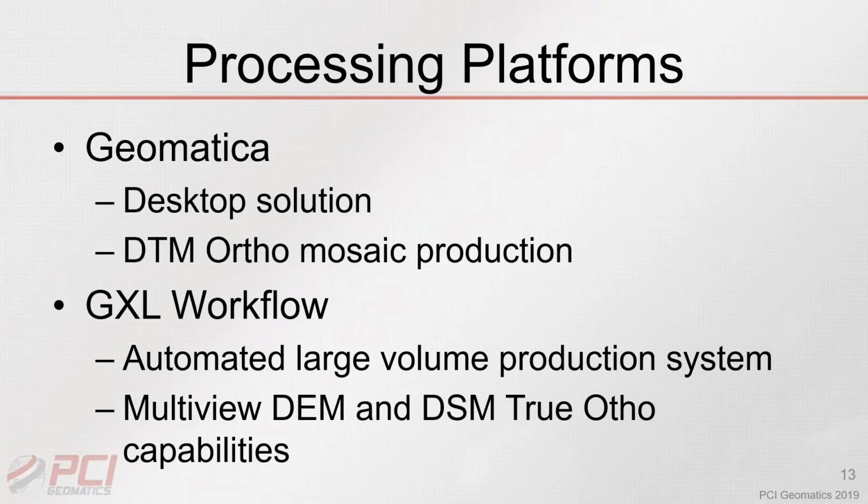then we have some specific optimizations that are part of GXL that are really going to take advantage of specific parameters for processing the data, to ensure that when we create the DSM True Ortho, we have fewer blunders and fewer artifacts in the data.